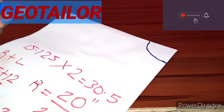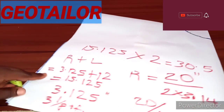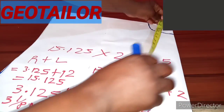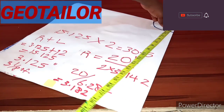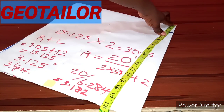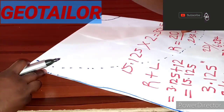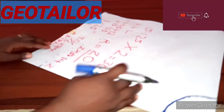So the next thing is to mark my radius plus length of skirt, and from our calculation here, our radius plus length of skirt is 15.125. So I'm going to mark from this center point 15.125. I'll mark it round to the other end and show us. I've marked my radius plus length of skirt round with a dotted blue line here. I'm going to connect it into a curved line.